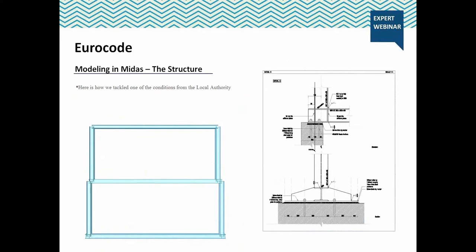In accordance with the conditions set by the local authority, we had to set back the 5th floor facade by 200 mm and the 6th floor by 510 mm from the existing brickwork. To achieve this setback and still keep the loads centrally over the perimeter wall, the ends of the main beams are cantilevered, and the effect of this created a staggered frame as shown. This is a detail of the cantilevering bearing pad.